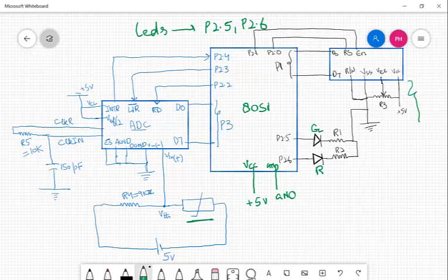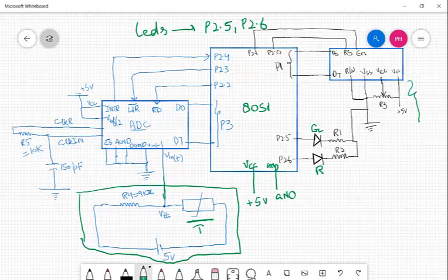At the input side, we actually have a thermistor whose resistance changes with the increase in temperature, and this change in temperature we actually convert using this whole module to the voltage change. So here we are getting the voltage change, but since this voltage change is analog in nature, we have to feed it to ADC before giving it to the microcontroller. So we feed it to the ADC using the pin V in positive, V in ground, V in negative, we ground this pin. And then in the ADC circuit we have three more pins we ground.